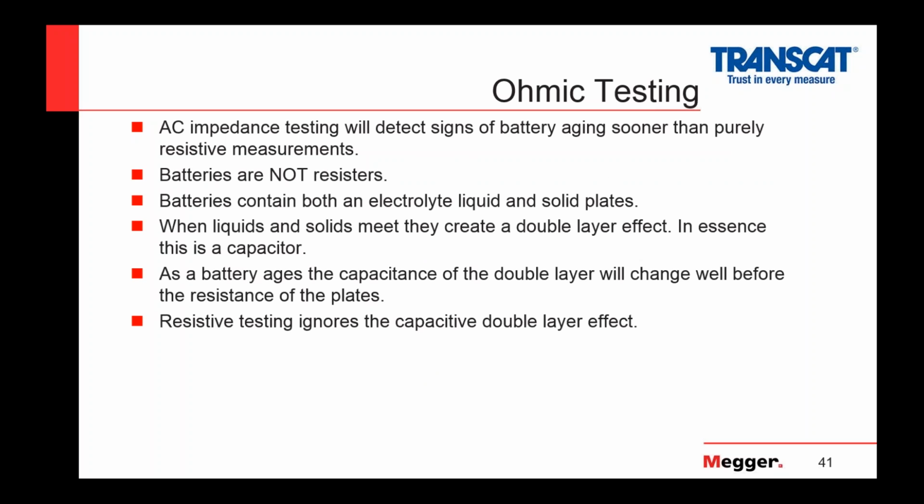Now, I said before that AC is not good to put through a battery, but we're talking about a small amount of AC and a small amount of time. So doing it for testing is not an issue. Okay? It's when AC is left on the battery for prolonged periods of time that you can get those heating effects.